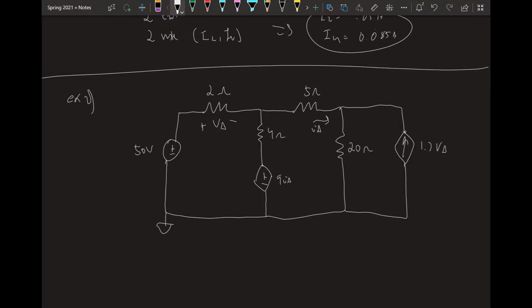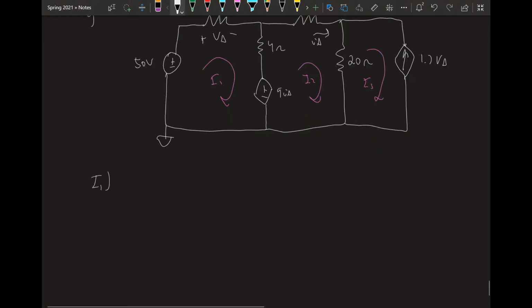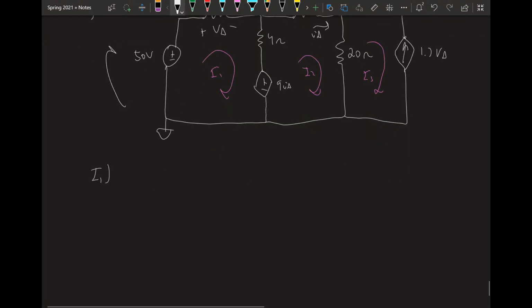Oh, let's define our mesh currents. We're going to go this way, and this way. I1, I2, and I3 respectively. And then we're going to write our system equations for each one. So, for I1, right, we're going clockwise. We go up in 50. That's a voltage rise, so that's a...